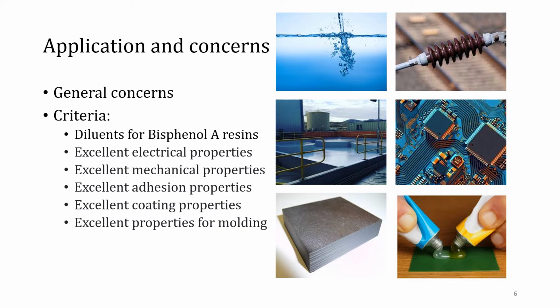The bisphenol A type epoxy resin provides the necessary tensile properties, and the mixture of the two is cured by a liquid anhydride with an appropriate compound as the accelerator. The system has been applied in winding wire. Its pot life is significantly longer than that of bisphenol A epoxy aromatic amine systems and is very useful.